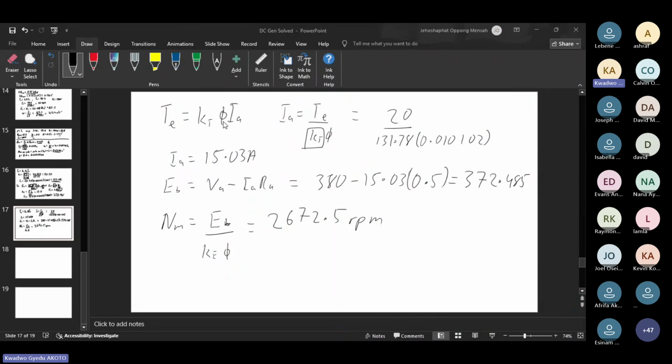So with the magnetism, because the midterm was asking about permanent magnets, I think it's safe to assume that your end of sem might ask about characteristics of magnetic materials that make them suitable for DC machines. So maybe everything from the BH curve downwards, right? High BR, high HC, good linear characteristics, and those things, right?